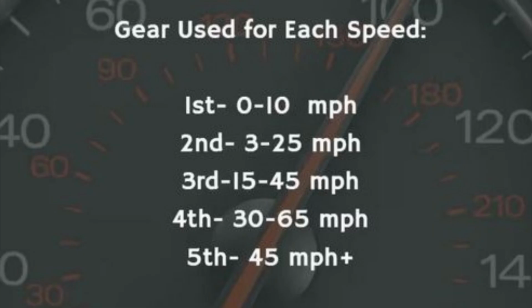Automatic transmissions achieve reverse motion in a different manner compared to manual gearboxes. Instead of using a simple idler gear, automatic transmissions rely on planetary gear sets combined with clutches and brake bands. Reverse gear operation is achieved by locking certain components of the planetary gear system, such as the sun gear or carrier, while allowing others to rotate. This controlled locking and releasing of components redirects torque flow and reverses the rotation of the output shaft. The process is managed hydraulically or electronically, allowing smooth and reliable engagement of reverse gear.